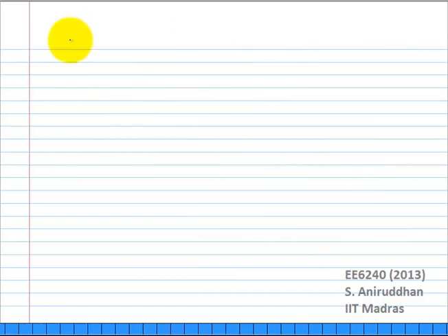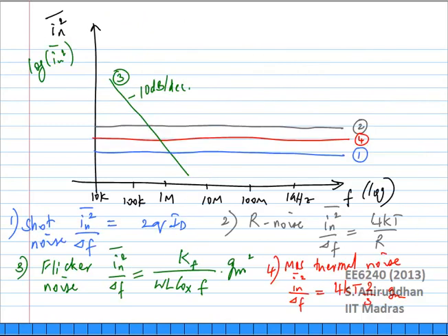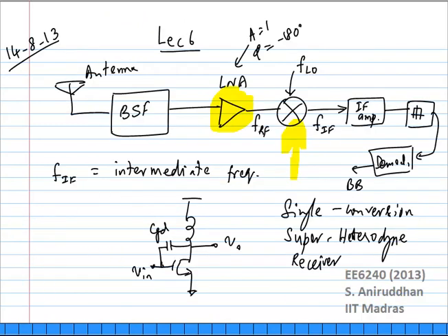Okay, so let us say, actually analysis of the band select filter should be very straightforward. All it does is remove the frequencies you don't want. LNA is just an amplifier. The primary thing which needs to be discussed is this guy. Is the mixer. Because we still don't know what a mixer does. All of you already know what an amplifier does, right? And even a low noise amplifier, you know what noise is. You are saying you want to amplify with very little noise being added. Even that seems very straightforward. Let us look at what a mixer does first.